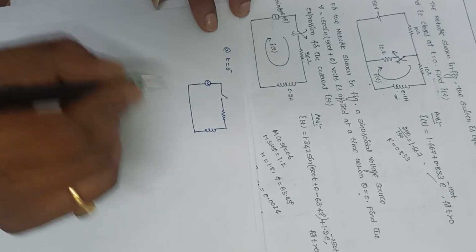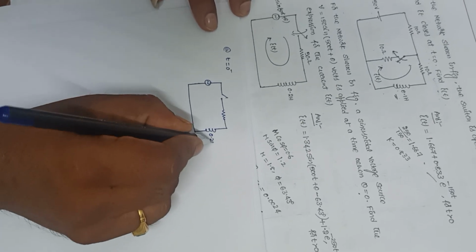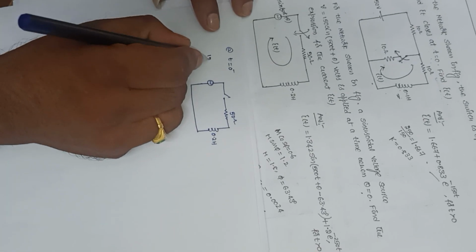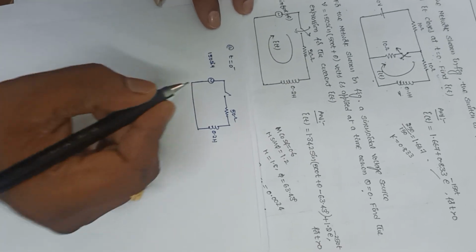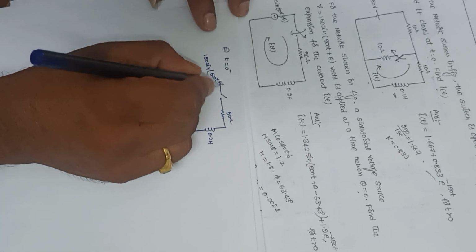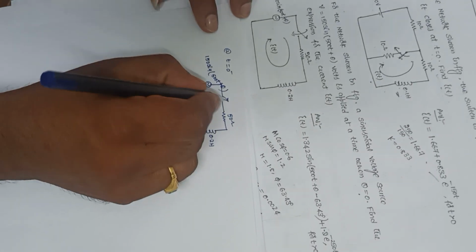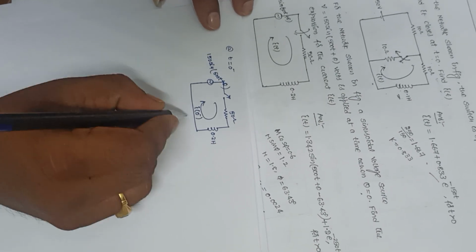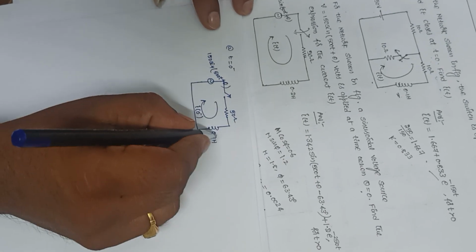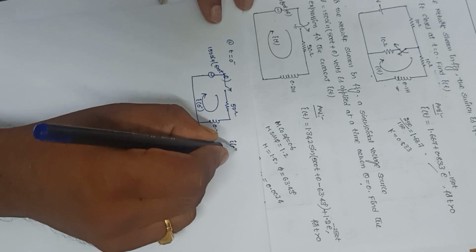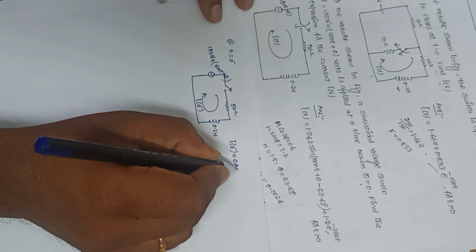Right. It is 0.2 Henry and it is 50 ohms. It is the voltage 150 sin(500t plus theta). So initially the current that is flowing through this is I of 0 minus. No supply is connected to this RL circuit, so the current value I of 0 minus is equal to 0 amperes.